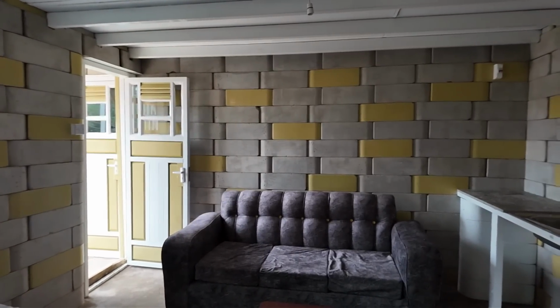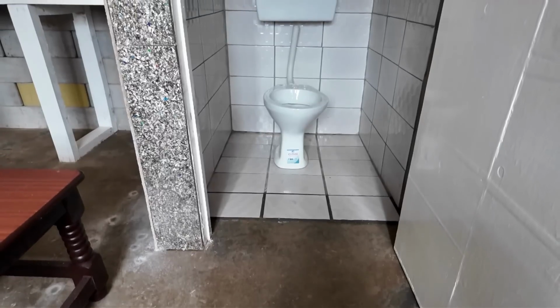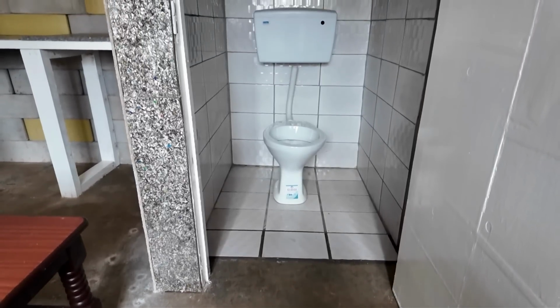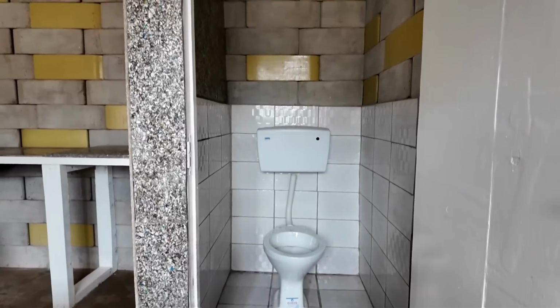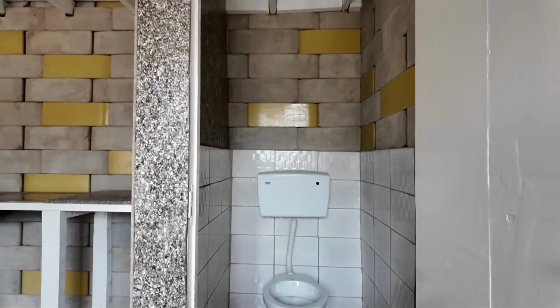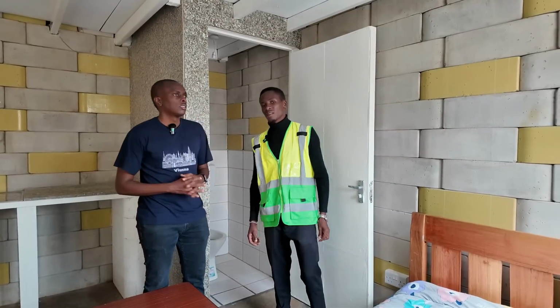Now, because of the smooth nature of the twist blocks, are they able to hold tiles properly? Yes, the smooth nature of the twist blocks is able to hold tiles properly. In the areas where we have the joints, you can apply some mortar, or rather cement, where you want to stick your tiles, and then stick your tiles appropriately. These joints give you a grip, but you could also at least scratch it with an angle grinder and then stick cement if you need.